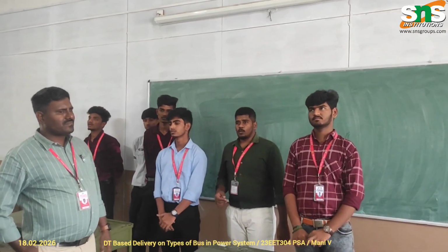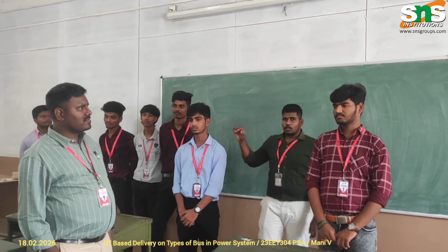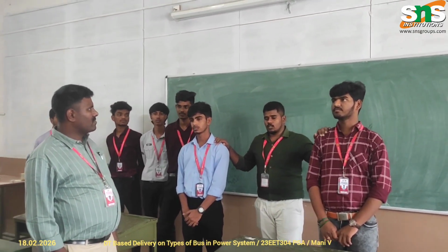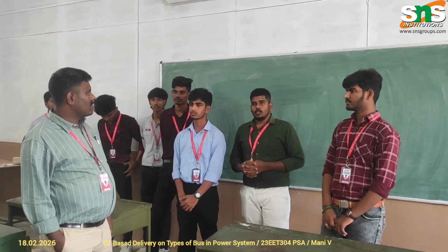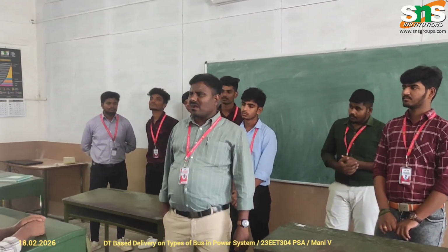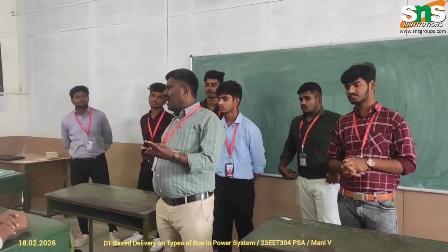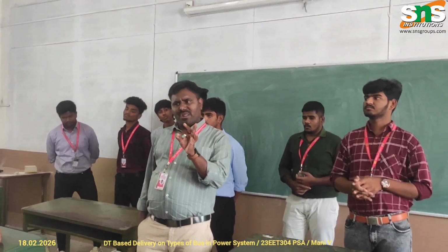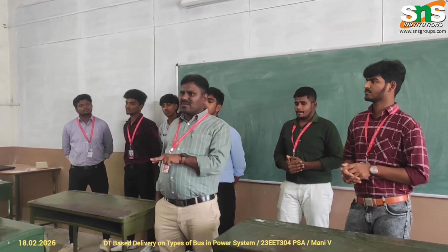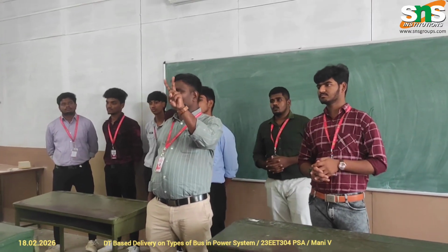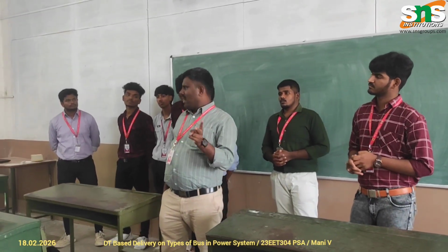Now the slack bus. It is also known as a swing bus or reference bus. Here the magnitude of voltage and the phase angle are specified, and I want to determine the real power and reactive power. So based on the four quantities, real power, reactive power, voltage and phase angle, for each bus two quantities will be known and the other two quantities will be unknown. For the generator bus, or PV bus, two quantities are known, and for the load bus only two quantities are known, that is, one is P and another is Q.